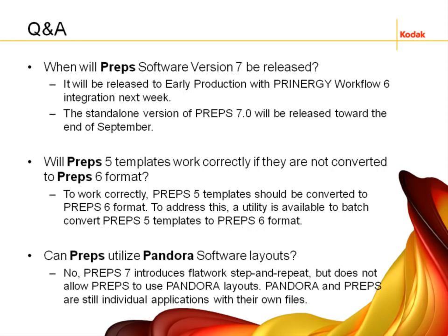Will PREPS 5 templates work correctly if they are not converted to PREPS 6 format? So to work correctly, PREPS 5 templates should be converted to a PREPS 6 format. Now, that doesn't mean you have to go into PREPS and recreate them to be the same. We have a utility that has been shipped since PREPS 6, and it's called the PREPS Template Migration Utility. You'll find it in your Utilities folder in your PREPS install.